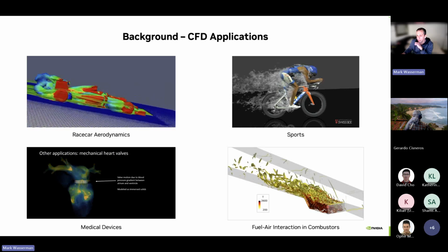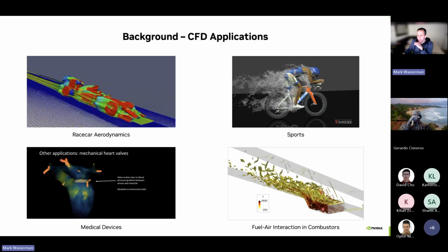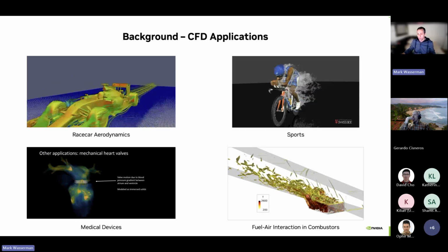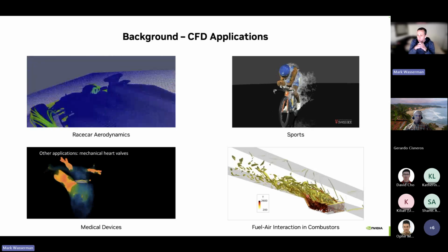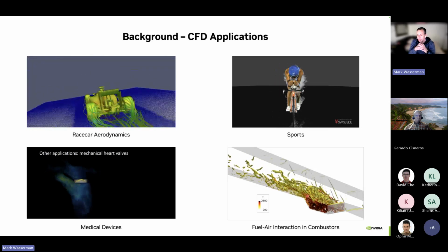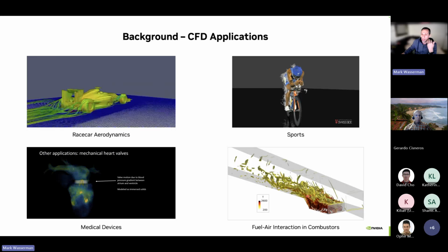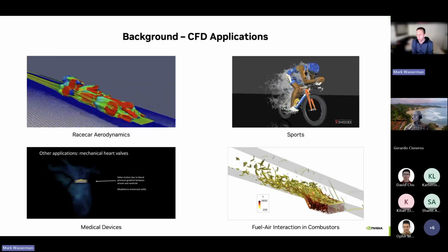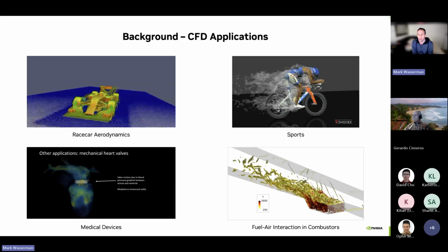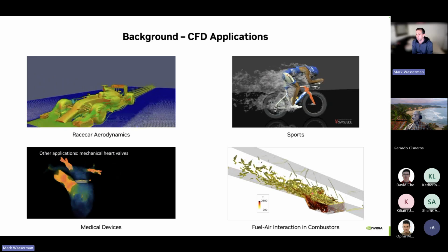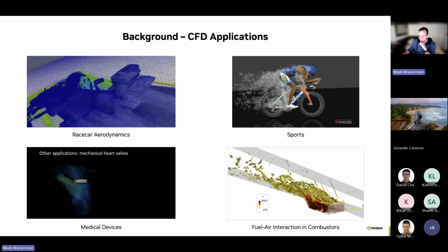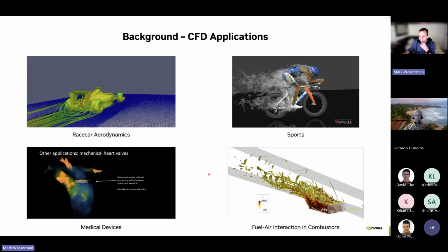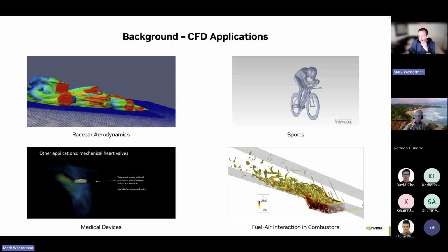So you can see here in this cavity, fuel that is at rest, but when the high-speed flow of air flows on top of it, it combines with the fuel, mixes with the fuel, and ignites, which serves as the basis for hypersonic scramjets and generally combustion at high speeds, which is different than combustion at low flight speeds.